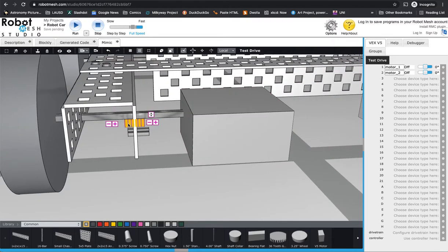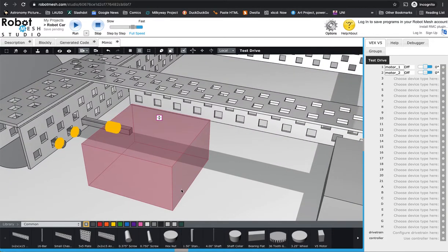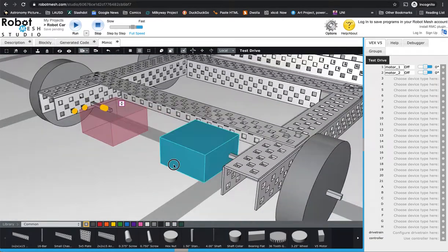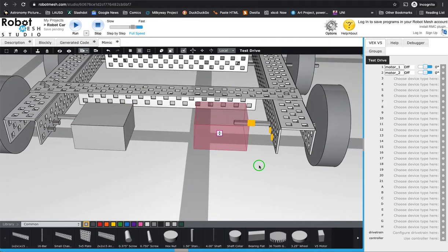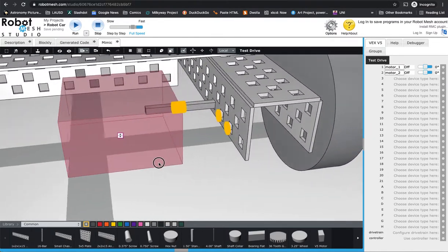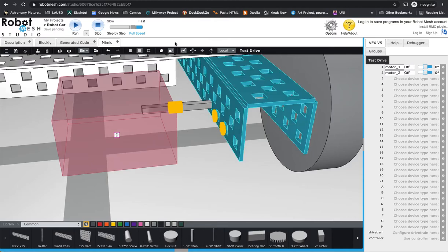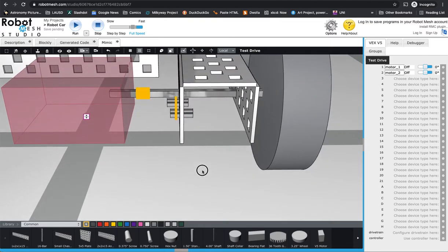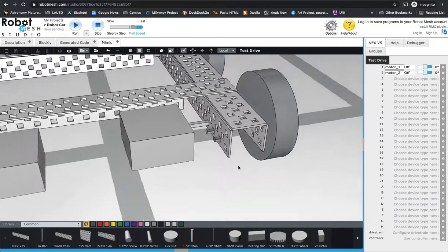Maybe move it a little bit this way. There we go, all lined up. So there's that motor attached. And the other motor, I need to do the same thing over here. So let's zoom in to this side. These two circles here, again, using the auto tool, 3.75 inch screw, attach it there and slide it in. And attach it here and slide it in. And just making sure. Great, both circles are attached to the screws, and the screws are attached to the bar.